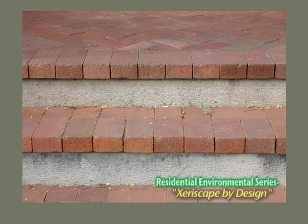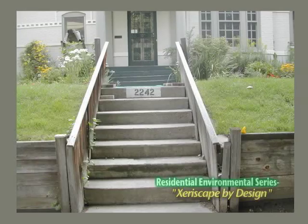Here we overlaid the pavers, again, on some existing concrete, and it was real old concrete in an old neighborhood in Denver. We just left the concrete exposed on the riser part of the treads. And these pavers are attached with glue, paver adhesive. And you can buy that product at Home Depot if you're doing it yourself. And they really stick. I have done this at my own house, and they haven't moved. Okay, so I didn't design that either.